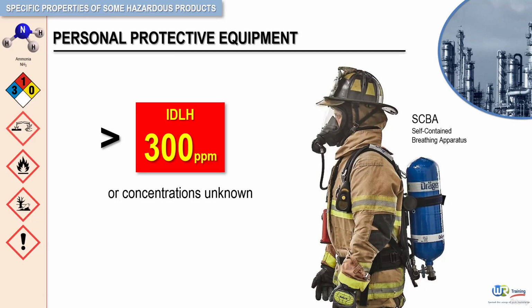If you are unsure how to use your respirator or have questions about cartridge selection or proper fit, stop and ask for help. Never rush to a scene without proper respiratory protection. Keep in mind, exposure to anhydrous ammonia can also be damaging to the skin and eyes. This is why various types of personal protective equipment will be required when working with or near anhydrous ammonia.